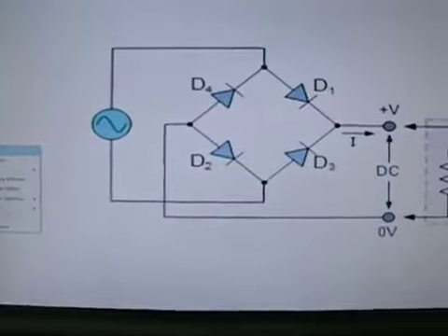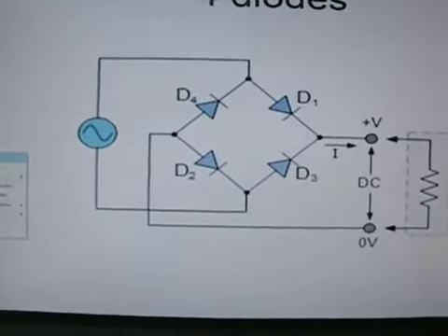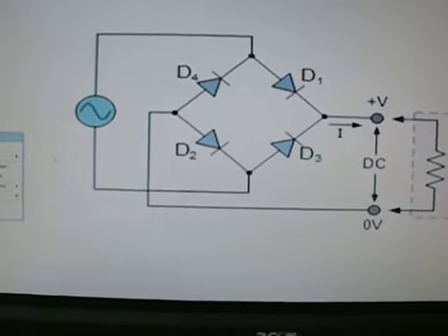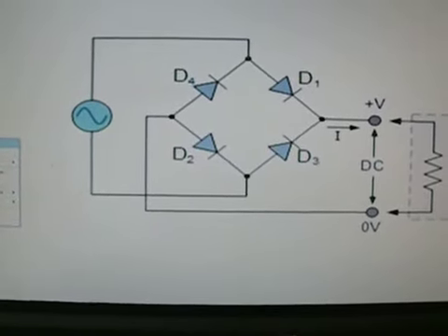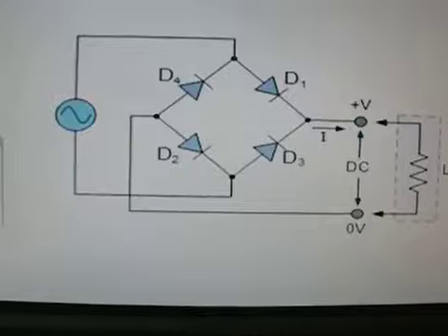2 diodes, around 80%. When you get to the ultimate configuration, which is called a full-wave bridge, that's 4 diodes. Here's a full-wave bridge. That was also on the initial drawing where I showed you how AC voltage is converted to DC. A full-wave bridge rectifier using 4 diodes is around 95% efficient. So they're very much a norm. Okay, so I told you about diodes, what diodes do. Absolute magic.